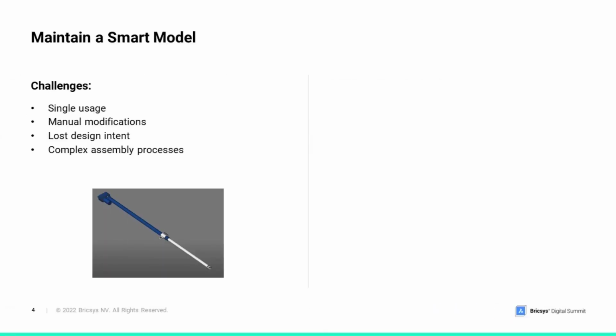Once having a completed design that initially fit the requirements, it's very tempting for the design team to call it finished. In reality, those designs will have to undergo several changes early and even quite late during the product cycle. By planning in advance, good product teams can create smart, changeable models that behave in predictable ways when modified. It is achieved by parameterizing the design.